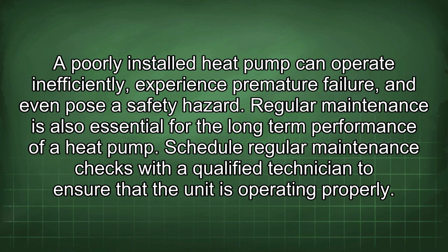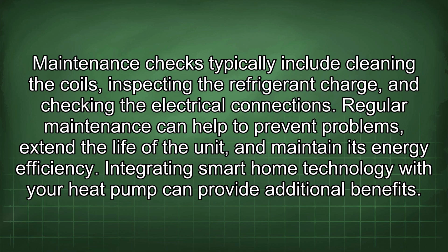Regular maintenance is also essential for the long-term performance of a heat pump. Schedule regular maintenance checks with a qualified technician to ensure that the unit is operating properly. Maintenance checks typically include cleaning the coils, inspecting the refrigerant charge, and checking the electrical connections. Regular maintenance can help to prevent problems, extend the life of the unit, and maintain its energy efficiency.